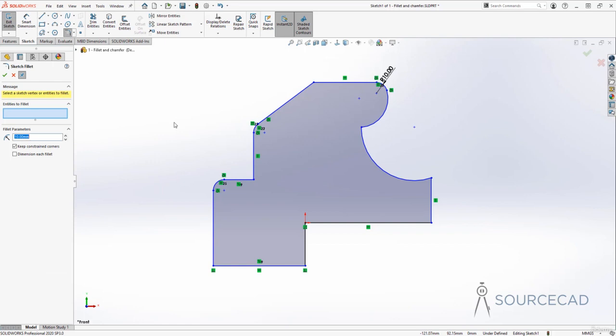All right, let's make it again. So I'll go to fillet, and once again, I'll make selection, but now I'll make it in a different way. So I'll just make a window kind of like this, a big window. And here you'll notice that all of these edges which are inside the window are now selected. So if you want to make a quick selection, you can do this using this kind of method. Now I want them to have different fillet radii, and for that I'll keep this one checked. I'll click OK, and every single fillet now has a different radius which you can change separately.